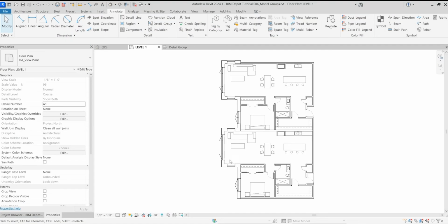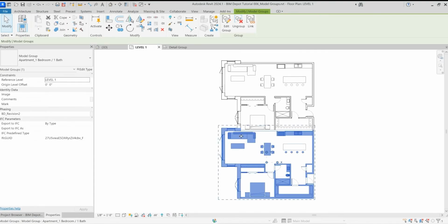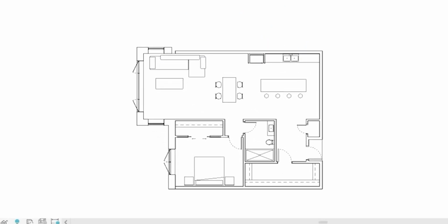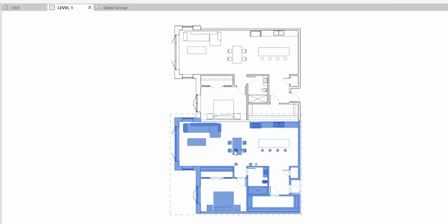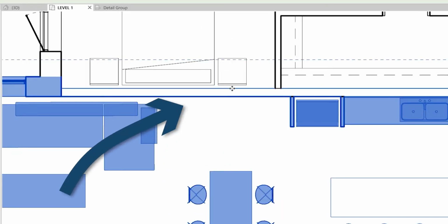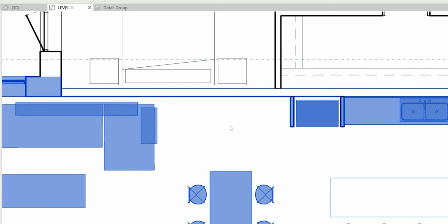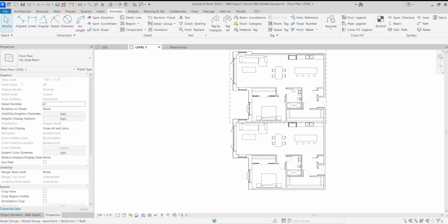One other issue that I've come across when doing this: you'll notice when we had the single wall here, we have a wall on both sides containing the unit. So if we undo that, you'll notice that if I click on this, this actually highlights blue along the edges, but the inside is white. The reason that's happening is because there's two identical instances of that wall in the same exact spot. There's a few ways that you can deal with that. Probably the best way to do it is to actually remove one of the wall sides.